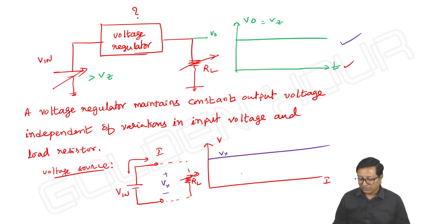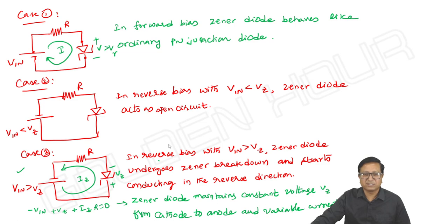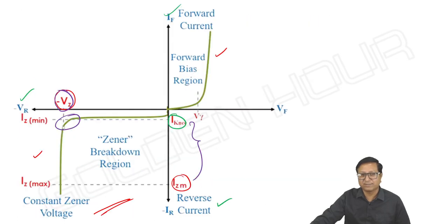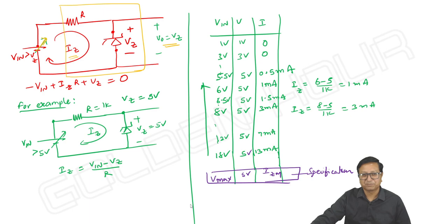Okay. So, that's what. We are designing a voltage source, only DC power supply voltage source we are designing. Regulator means what is output, right? Here, it is something like this. This characteristic and this characteristic are matching. Okay, so such thing is possible, we need to discuss how it is independent of RL, except that, right, the Zener diode is exhibiting a characteristic of a voltage source with some limitations on its current. You cannot take IZ for any range. There is a minimum limit and there is a maximum limit.